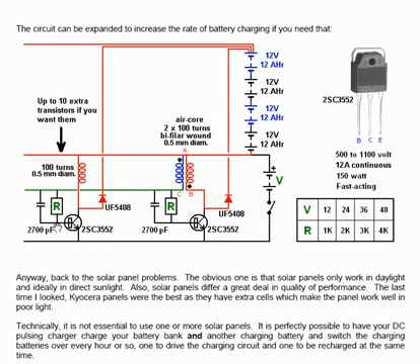It's more effective if each particular section has its own wire feeding to the battery bank. That is a more effective way of feeding a battery bank than just linking locally short lengths of wire to the built circuit. Anyway, go back to the solar panel problems.